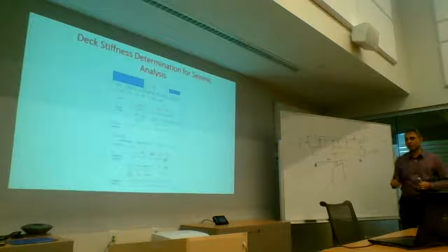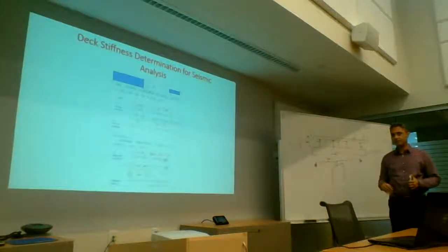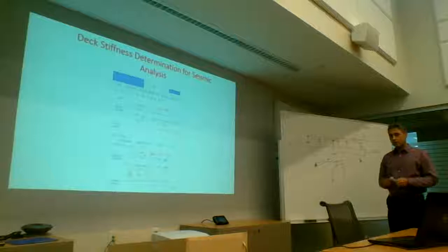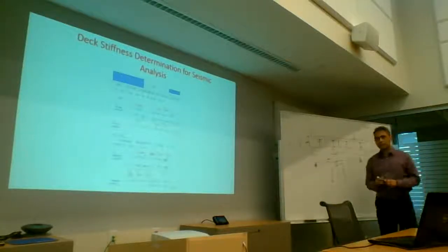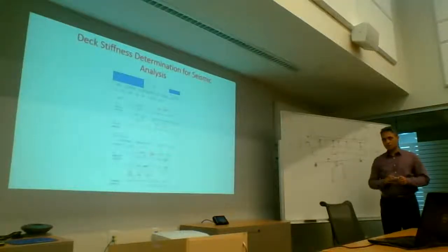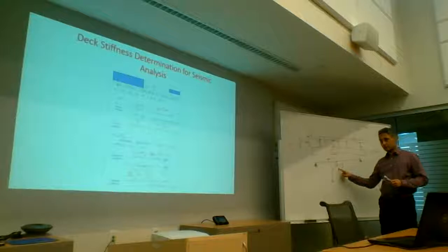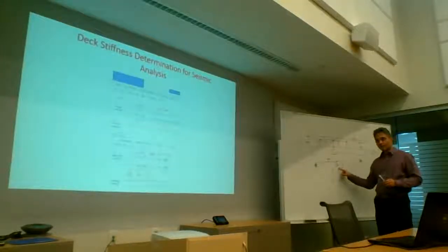the center of gravity of the system. So if the span on the left and the right side are different, don't we need any for the torsional effect on the cap beam? Will the rigid element still be okay? Yeah, it's a rigid element that you can use. It's fine because the stiffness will come into this beam itself. So you've got to capture the appropriate torsional stiffness of the cap beam.